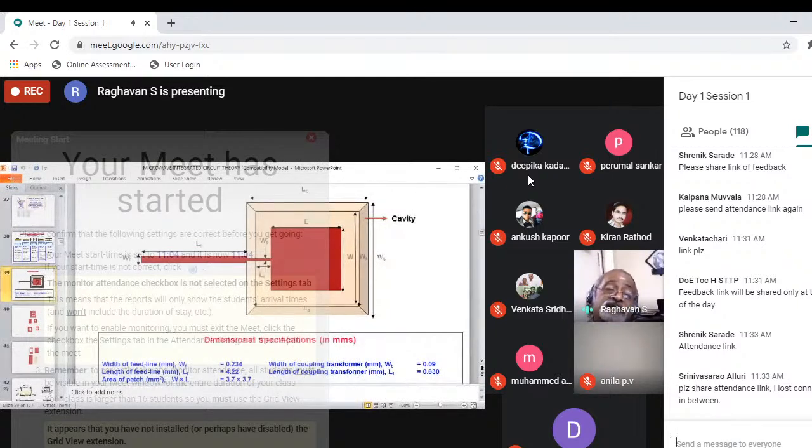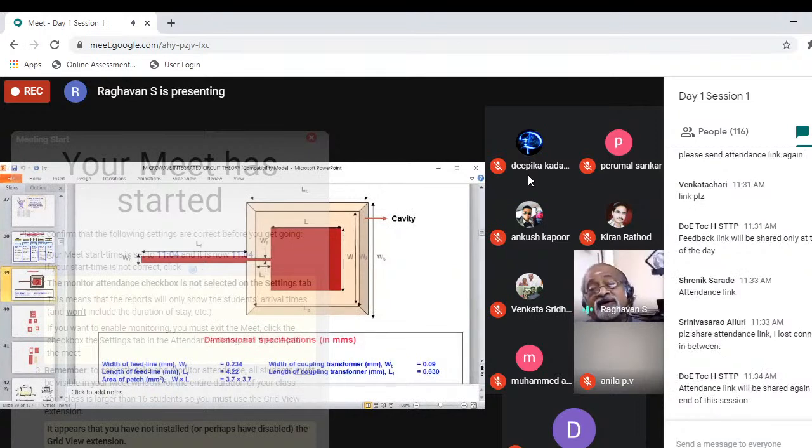It has three major components. The patch, whose impedance you can find out. Then the 50 ohms line. And if the 50 ohms line has to be connected to the patch impedance, you should make use of the quarter wave transmission line in a simple way. That's how the central line has come. You should find the root of ZS, ZR to get the impedance. That impedance is more, which is why the central line's width is lesser. The left side is the 50 ohms line and the other one is the patch.